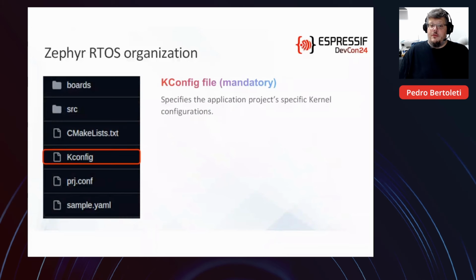The Kconfig file is also mandatory, and for those who are used to developing with an embedded Linux environment, or developing embedded Linux solutions, it works the same. So the Kconfig file here specifies the application project's specific kernel configurations.